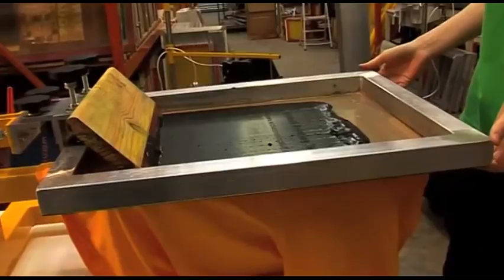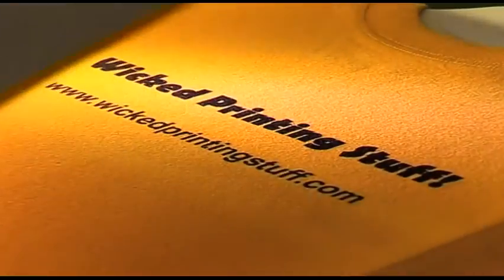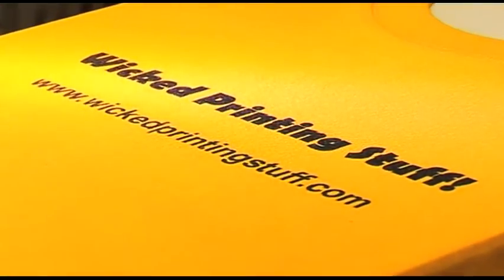Our printer prefers to draw the squeegee away from him as he feels it is more controlled and allows more pressure. Apply 1 or 2 coats of ink if required. Place your squeegee at the far end of your screen, resting against the head, and lift your screen to reveal your finished printed design.